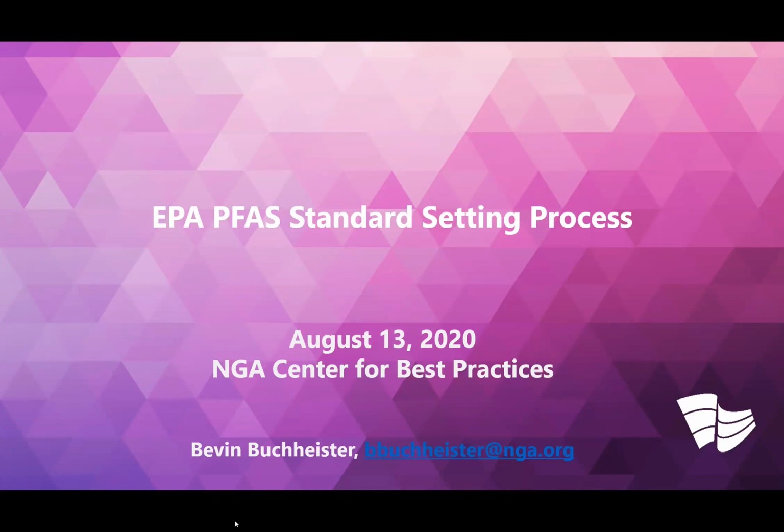So EPA has been taking actions on PFAS for many years, and in 2006 they initiated a voluntary industry phase out of PFOS and PFOA. In 2009 they issued a health advisory of 70 parts per trillion for PFOA and PFOS in drinking water. In 2012 and 2015 they did nationwide testing to determine exposure levels. And in 2019, they released the EPA PFAS Action Plan, and in 2020, they released a preliminary determination to regulate PFAS in drinking water.